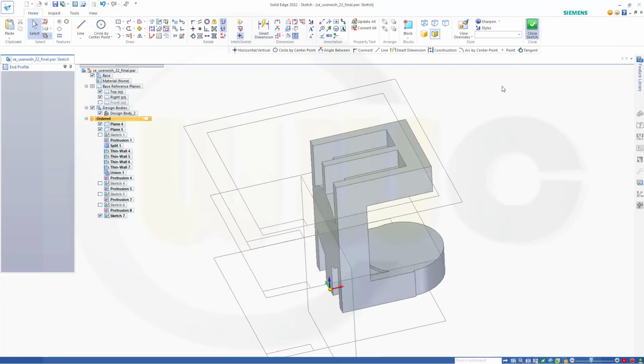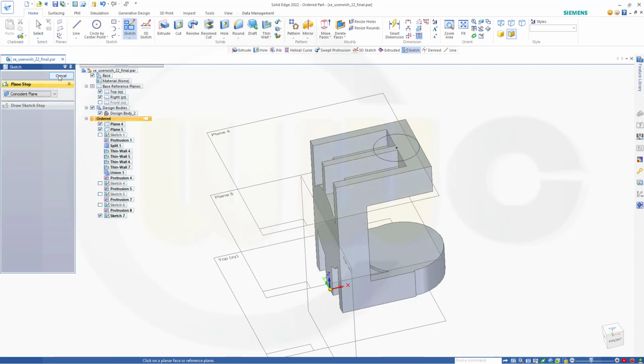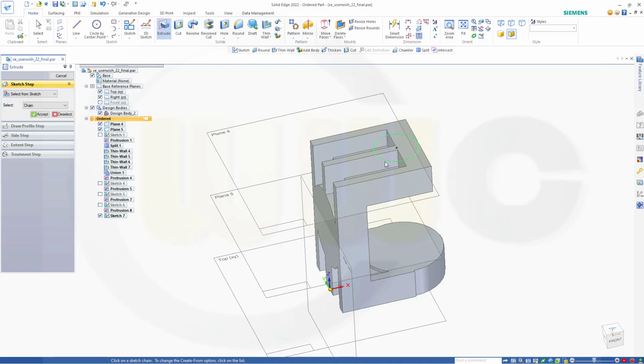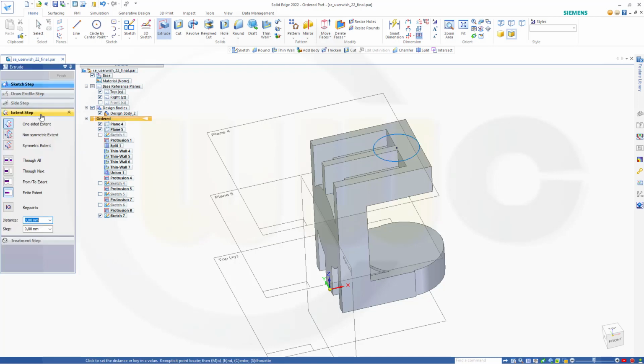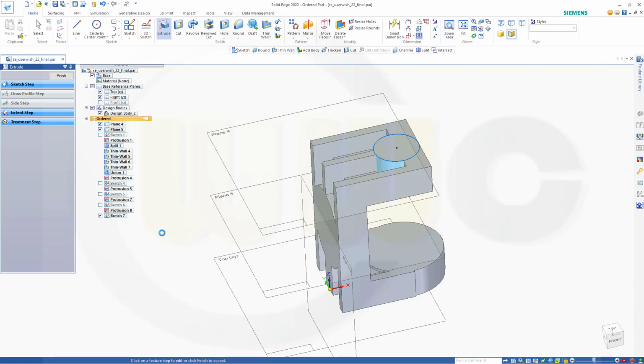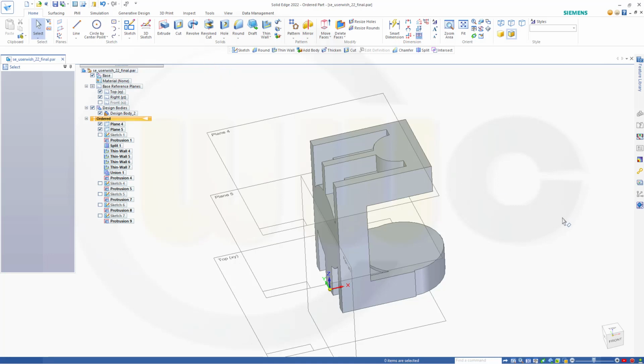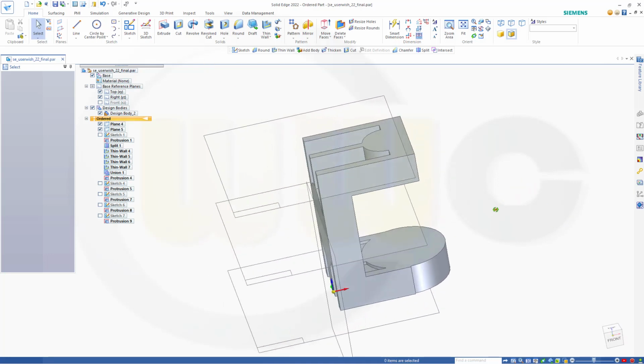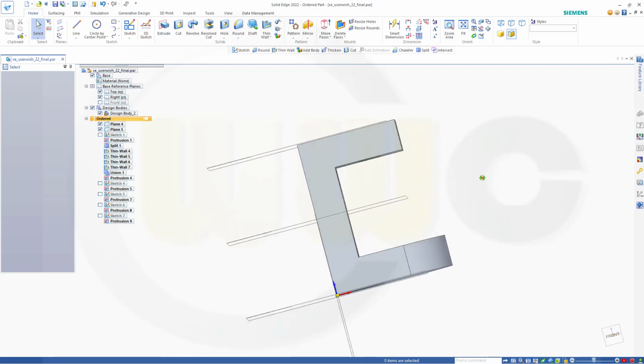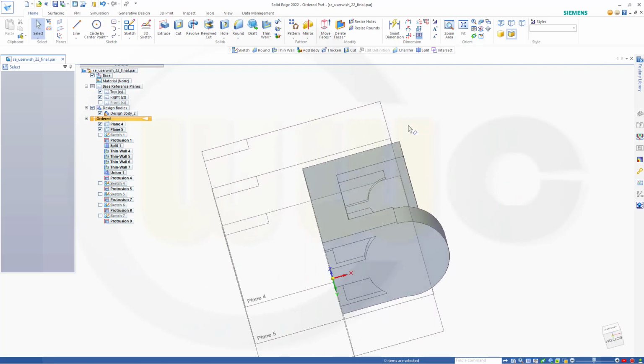Okay, close that sketch. Finish, cancel this out, make another extrude. Select that circle, accept, extend step yes, and again it's 20 millimeter in that direction. Finish, cancel this out and hide that sketch. Now I need a cut. No, first I have to do the holes, not the cut. So maybe show those sketches.